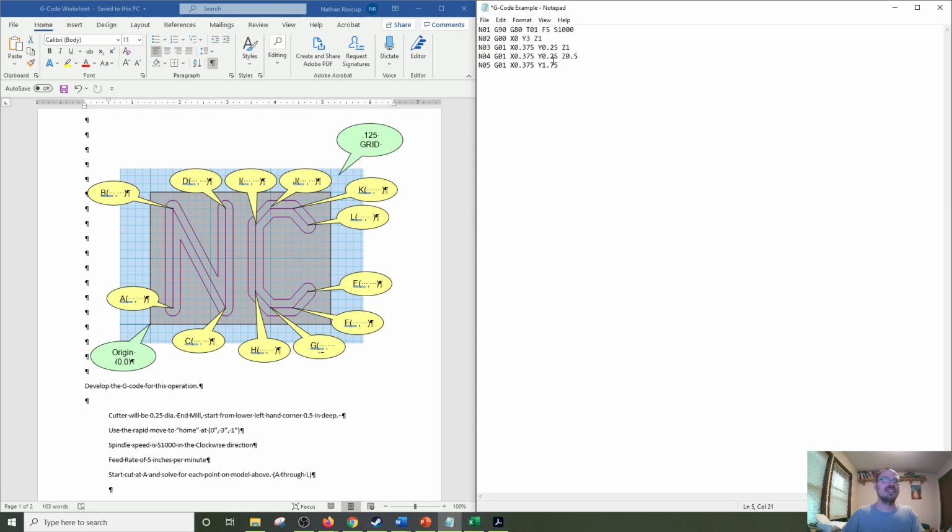All right, so that gives us A to D, A to B, and again, you just keep going along that line. So you follow the G01 commands all the way through. And then again, lift up here at D, because you don't want to cut through all this when you're moving to this point, right? You'd cut right through that. So you have to lift up to 1 inch. In this case, we'll just stick with 1 inch. Move over to the beginning portion of C, and then follow through to L. Yeah, E through L for C. But that's the general idea.